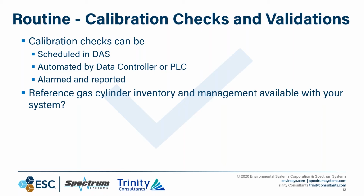Get it in there, get everything validated. Hopefully there were no problems, you had enough bottle pressure, the analyzer has been maintained properly, you don't have any leaks in the system to overcome, your cal is passed, your data is validated, and life can go on.